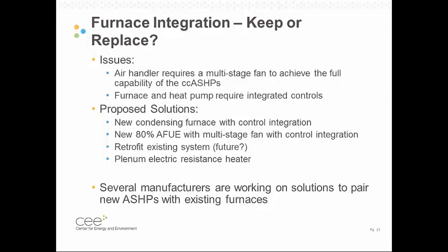So I started to talk about this a little bit, but the furnace integration in particular is a new area for manufacturers. With a traditional heat pump system, before we had the cold climate heat pump systems, there were heat pumps that were available. They just couldn't really heat beyond about 30 degrees outside. And so in our climate, it wasn't really considered a heating option because so much of the heating season is below 30 degrees. And those older systems could really be installed with any existing furnace out there because they didn't have a lot of integrated controls. It was really just, is the heat pump on or not?